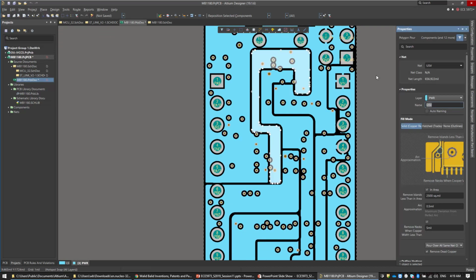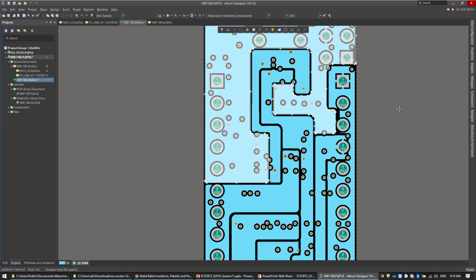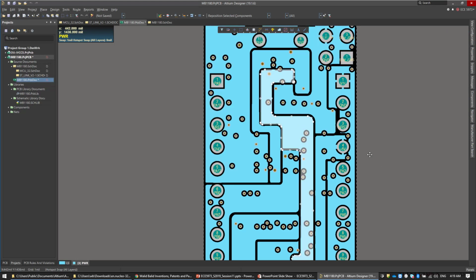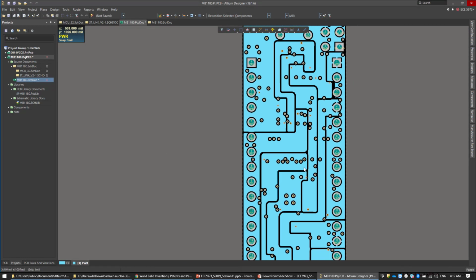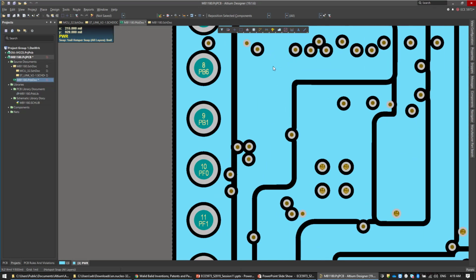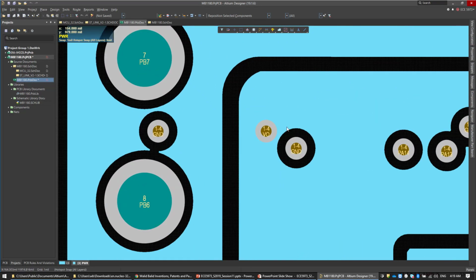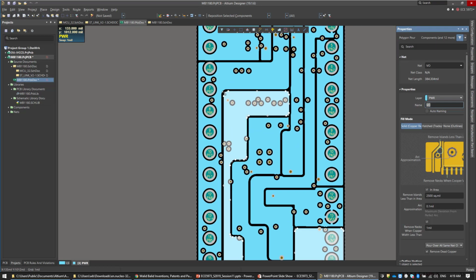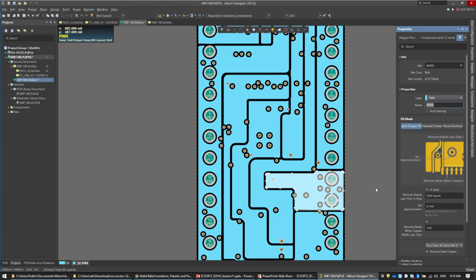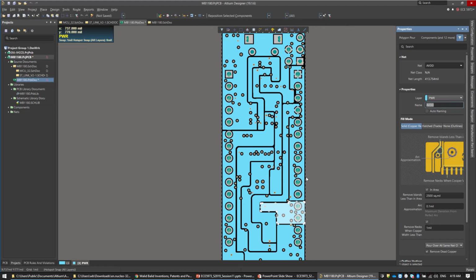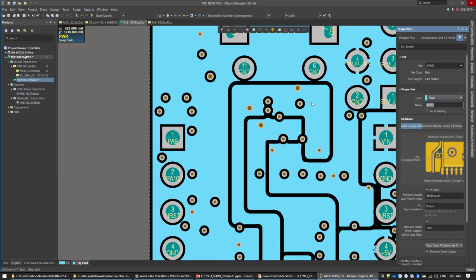And then they have this section. This is U5 volt. This is coming from the USB interface. And they have this section. This is E5 volt. This is like an auxiliary power supply. And they have multiple power supplies on this board because you have different options. This is VO, voltage output, and then they have this. This is VDD. They have this. This is 5 volt, and they have this. This is analog VDD.